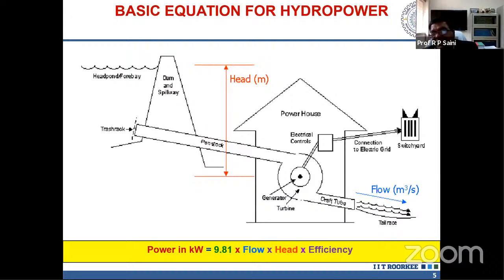And then finally, this mgh. So that means the power equation is a derived term. Of course, it is derived from mgh, but after conversion. So finally, this is the power equation: rho g, where 9.81 is g, into flow rate in cubic meter per second, which I think is written over here, and head in meter, and the overall efficiency of the system.